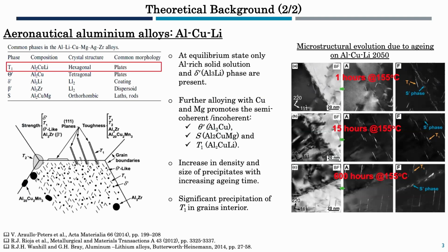The most difficult part with this kind of material is aging, because just like human beings, aluminum alloys also age. They age by reducing their mechanical performance, but they also introduce some precipitates in their microstructure. We call it artificial aging, simulating natural aging. You can see these small precipitates, of the order of magnitude of nanometers, that hinder the dislocation movement, and then alter the mechanical performance.